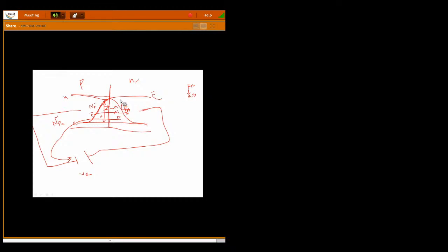Now what is the case? Even when you are turning to the reverse bias, a large amount of current is flowing. What is that large amount of current? These minority carriers are moving from the N region to the P region and from the P region to the N region. That minority charge concentration current you call the reverse saturation current, but that is a very small current. Still, that current is flowing through the diode, even in the reverse bias case.